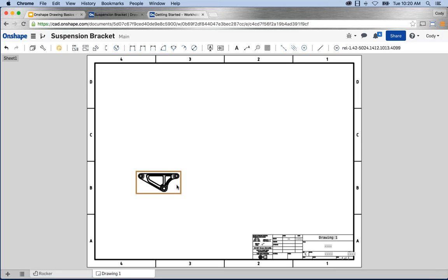Okay, so I've inserted my first basic drawing view. Front view, very simple. I can go back to the drawing view command, which is the very first view tool here. Select drawing view. I can select the part I want, and the orientation I want. So again, if I needed to insert a right view, for instance, or an isometric view in the corner, I can go back to the same drawing view tool that we used just a moment ago by selecting this icon in the toolbar and choosing my view. So that's another way of getting your standard views into your drawings. Front, top, right, isometric. You just select drawing view and then select the view type. Okay, again, same functionality that we saw when we first created the drawing.